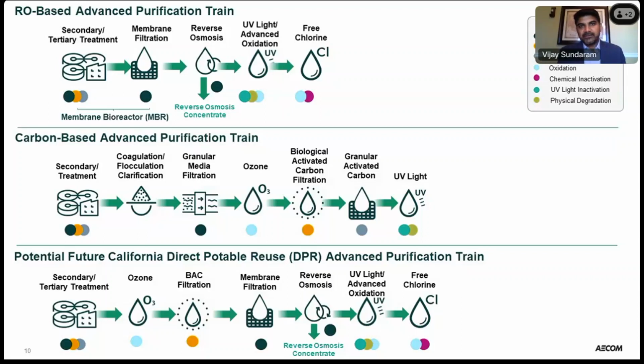So that's where carbon-based systems utilizing ozone biofiltration and granular activated carbon come in very useful for those communities. A lot of my personal research and doctoral work is on this carbon-based system, and how we can prove that in terms of contaminant removal, it will not be able to touch the TDS, salts and total dissolved solids, but it will be able to go after the pathogens and organics, bulk organics, and CEC, such as hormones and pharmaceuticals.